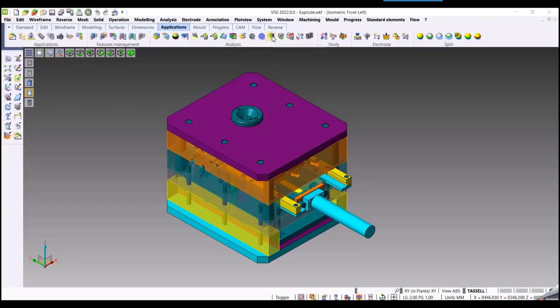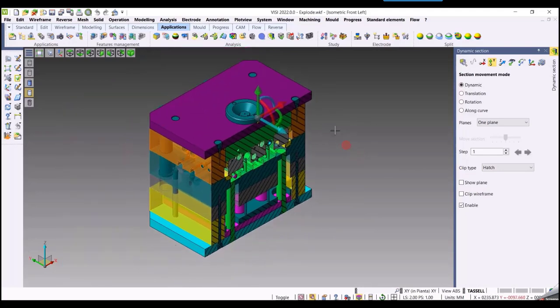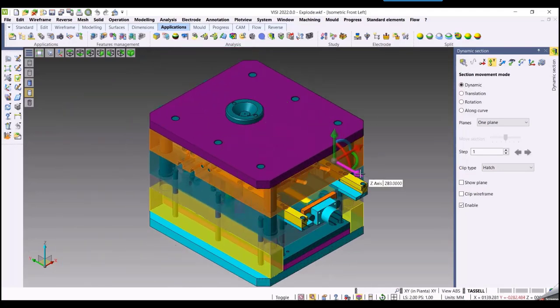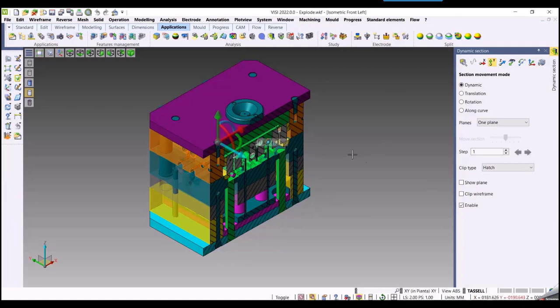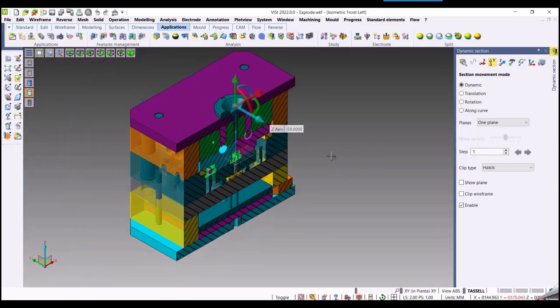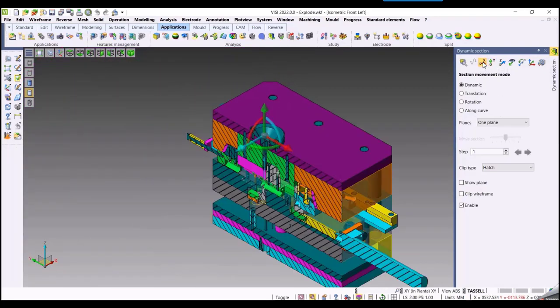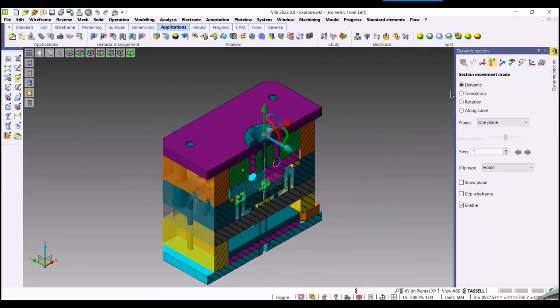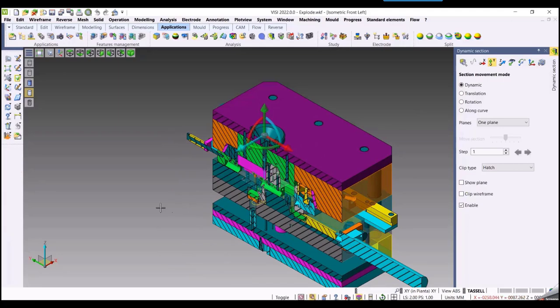So here's just a quick video demonstration of that. You can see we have the dynamic section, and we have a new option for dynamic. You can do the dynamic section off of 1 plane. You could change that drop down in there, and you can select 2 planes. You can change the rotation center. You can change your options as well to change where it's going to actually create the section. I'm simply holding the Alt key, and you can change that section in relevance. Change the X, Y, and Z values, and so on. You can even rotate this section too.